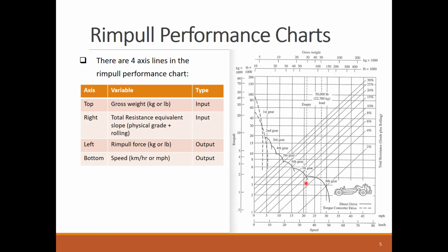You can easily relate to this chart if you drove a manual transmission car like me, or know how the power transmission system works. The gear performance curves form together the inverse relationship between machine power and speed, which we covered in the last lesson. The higher the equipment speed, the lower the Rimpull it can provide. The first and second gears provide the highest Rimpull, but the slowest speed. The 8th gear provides the fastest speed, but the weakest Rimpull force.